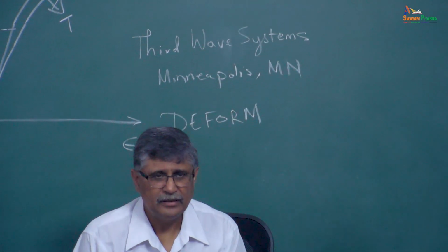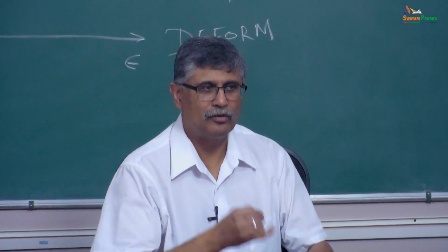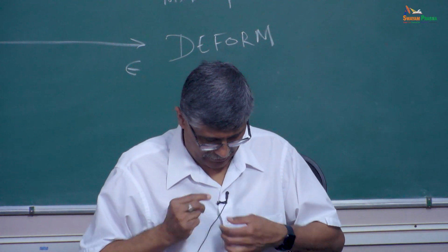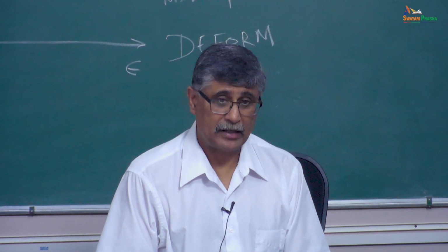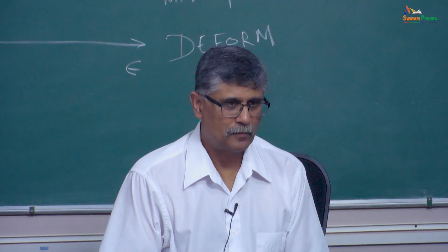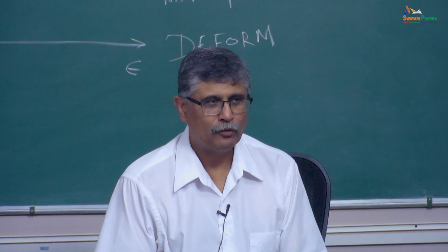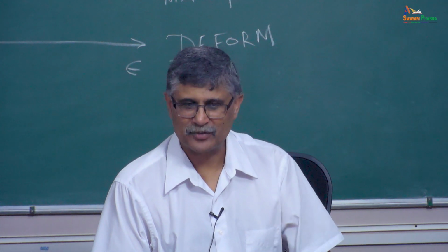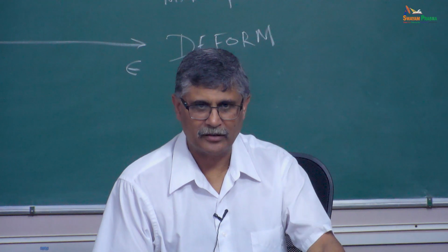Deform is another software. It was actually developed for metal forming simulations, which also involve finite plasticity type of problems. And so Deform can be used for machining also, okay? Beyond these two are the most widely used. People have tried using Forge 2D, Forge 3D. They're all forging, adapting it for doing machining simulations, but they're really not designed for it. The one that is specifically designed for machining is Advantage.